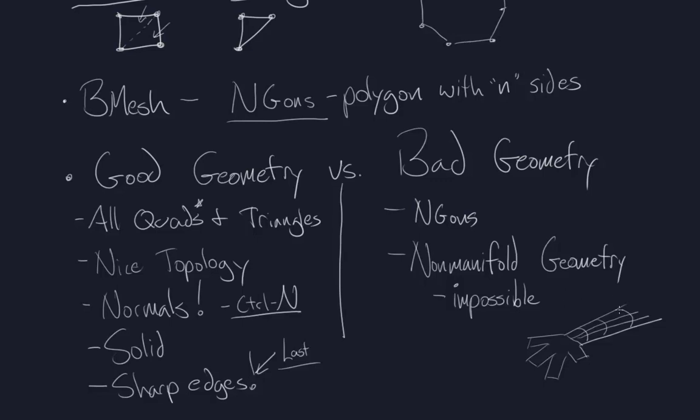However, sometimes if you're not careful, maybe based on how you extruded the shape, or maybe based on a whole bunch of other factors, inside the arm you might actually have a completely solid face. Because maybe at one point this was just a stump, and for whatever reason you extruded this, or you extruded it twice and didn't think about the other extrusion that you created, and you end up with faces inside your model. Watch out for those.